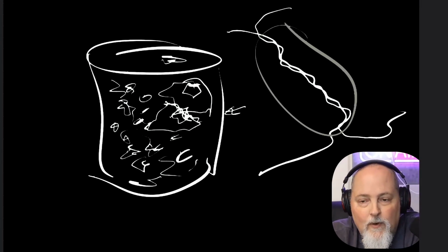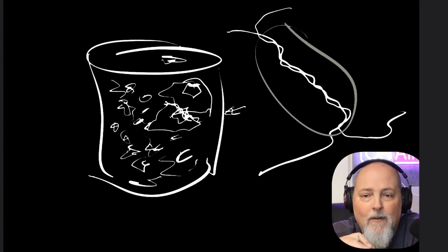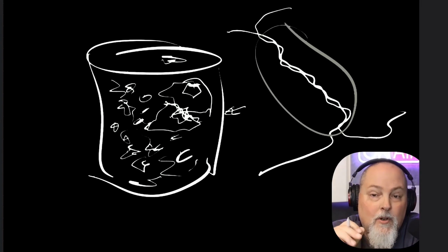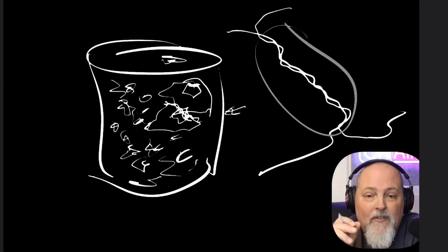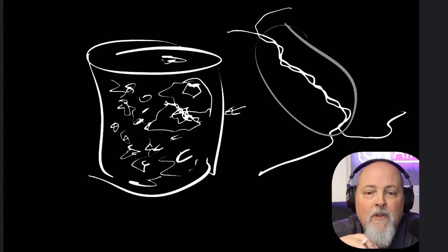So now what is creep? Creep is slow, permanent deformation under constant stress. Well, think about this and think about a nuclear reactor. Slow, permanent deformation under constant stress at elevated temperature. Our reactor plants, the reactor vessel, the core vessel, is under a constant pressure, over 1,000 psi, and high temperatures. It is extremely susceptible to that creep.